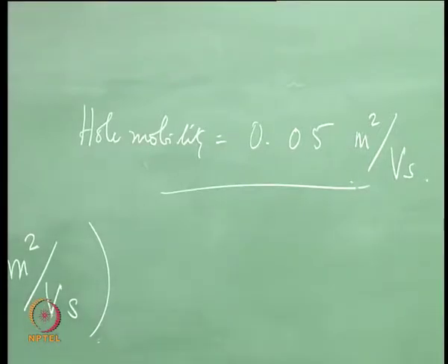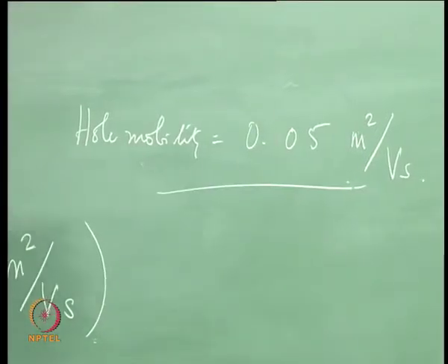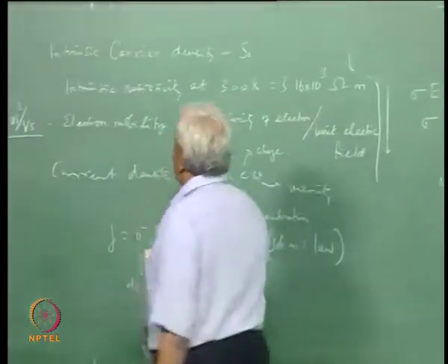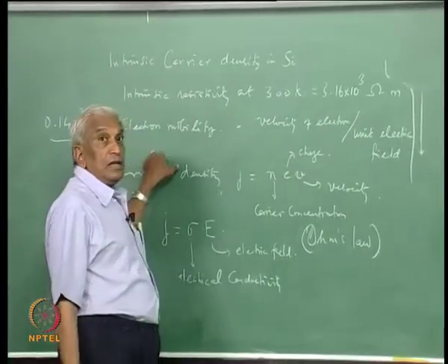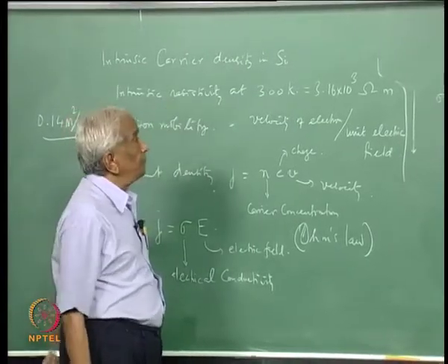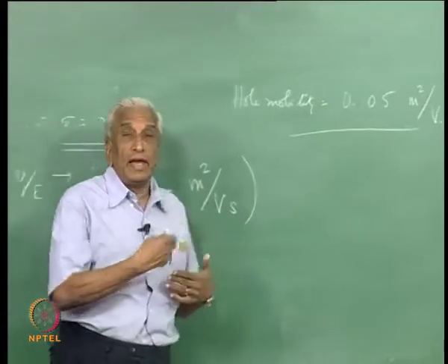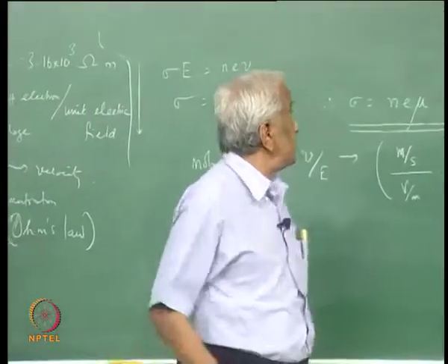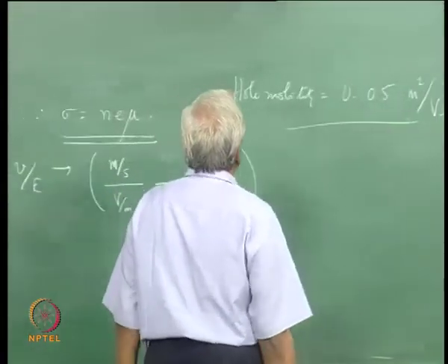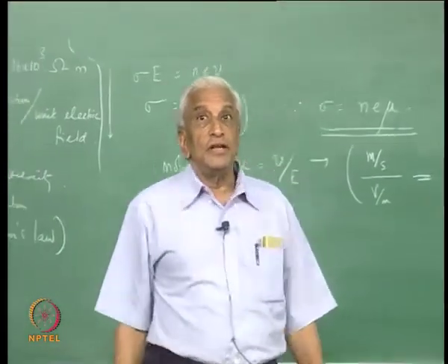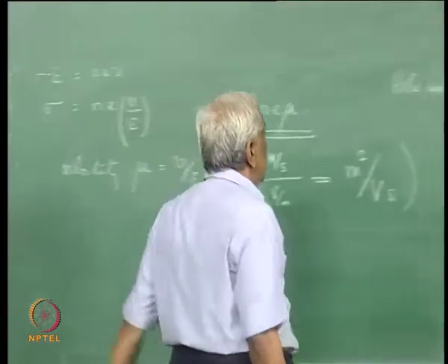The current density is due to the presence of both electrons and holes in the silicon. There is a contribution from the motion of electrons among states in the conduction band and also the motion of holes in states in the valence band.